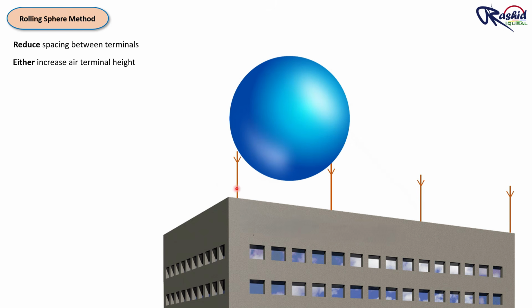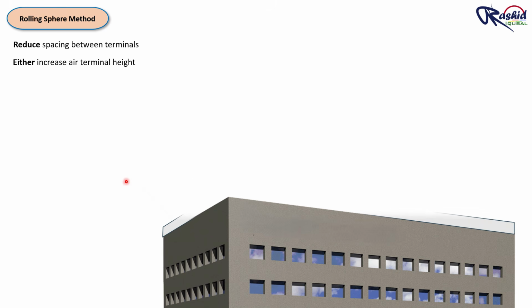But if you want to save cost, then there is a practical way to increase the height without buying a new rod. First, you can place the rod on top of the parapet wall. This effectively increases the height without changing the rod itself. Otherwise, use a concrete block below the rod to raise its height.